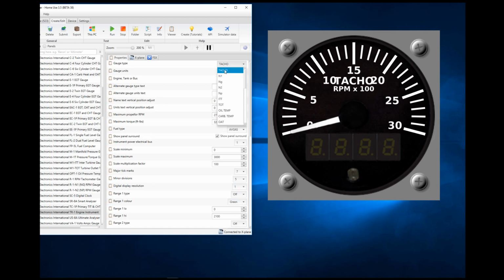If we base it on a tacho gauge for the purposes of this, at the end of the video I've got a little panel to show you I've set the user properties on a cluster of 8, like you'd get in a typical engine instrument cluster with the different gauges for a turbine. So I've got a cluster of 8 gauges set up differently with the user properties, but it's essentially the same instrument, just configured in 8 different ways. We'll concentrate on the tacho one for the moment.